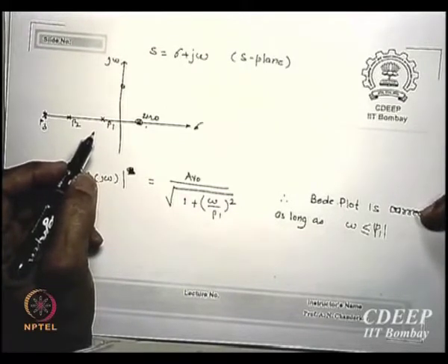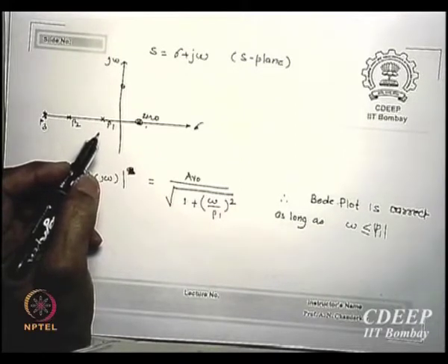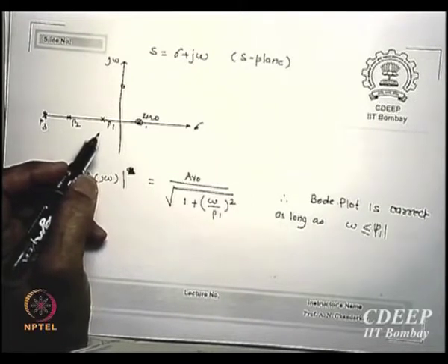What does that mean? That the gain starts increasing and not decreasing, is that correct? And if it keeps increasing toward infinity, the system will go to VDD, the power supply maximum voltage, so it will start saturating out, so it will not remain an amplifier, so we say it becomes unstable, is that clear? So we want to see the system remains an amplifier.